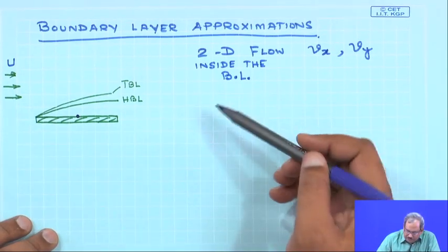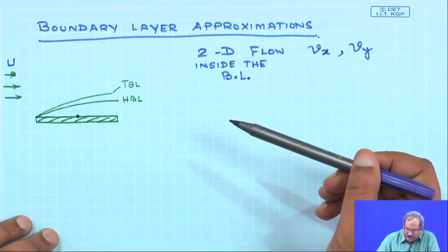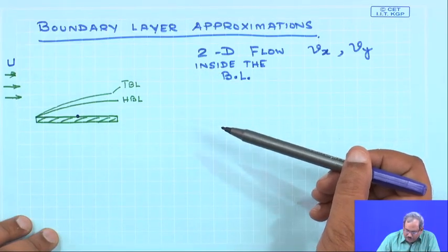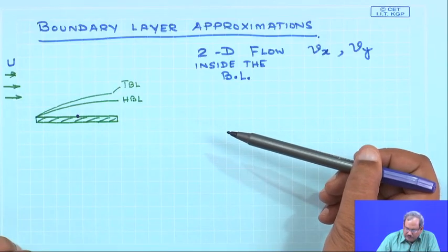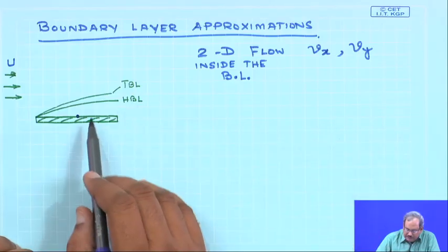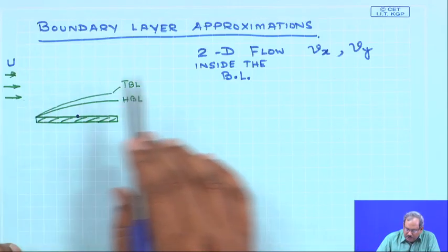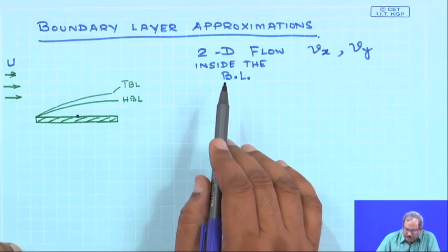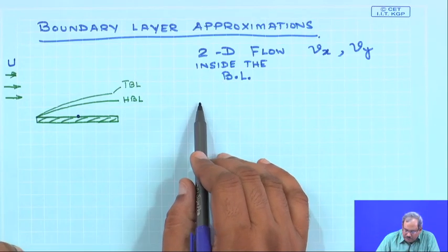The concept of boundary layer and the associated analysis together play a very important role in evaluating any transport process taking place near a surface when it interacts with a moving fluid. So, it is important in momentum transfer, heat transfer, and mass transfer.